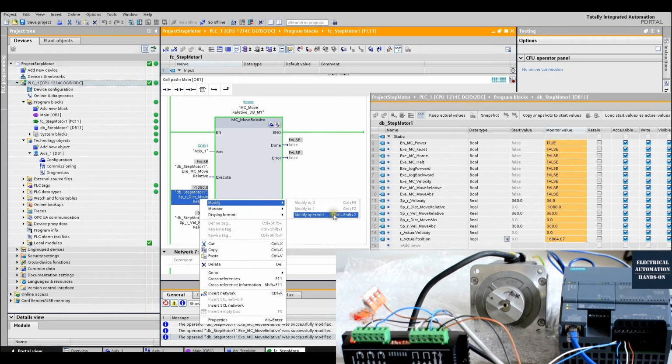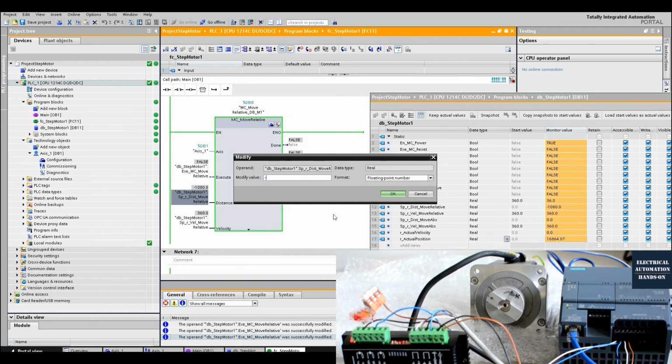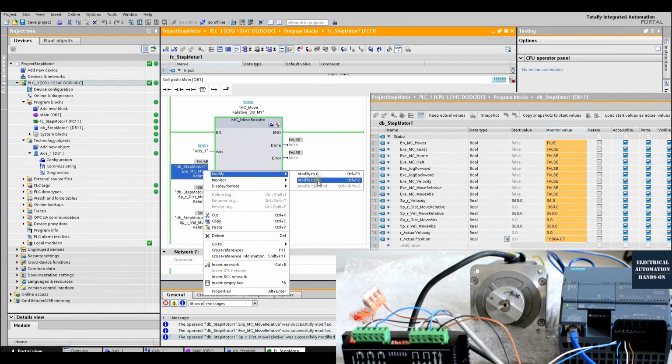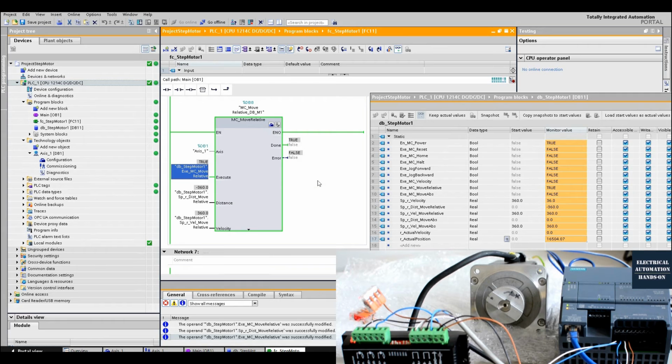Okay, if I set 1 revolution, negative 360, with this speed, trigger, 1 revolution. The beauty of the step motor is that it is cost effective and does not need an encoder, because the step motor is controlled by the number of pulses used to control the position. So it's still running basically accurately, unless your mechanical has slippage inside. Now this is the current position. This is relative. This is our current position.